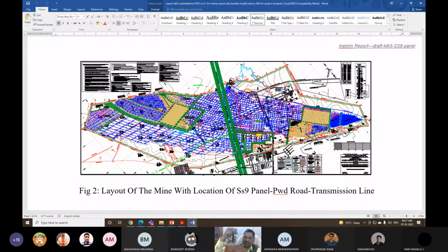So these two openings can be made like this, but here if it is 1 in 1 or 45 degree, or 1 in 7, 1 in 4, right? Whatever inclination we are having here, that will become so steep. So now instead of along true dip, if I make a gallery or the entries like this, how will it be? Now this inclination will not be this steep. If it is 1 in 4, this may be 1 in 6.